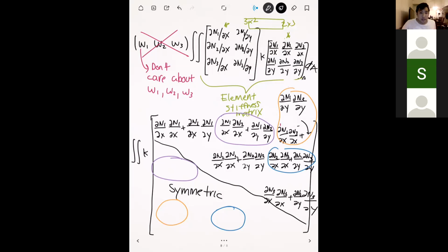Okay. So it's a doozy. It's a lot of calculations, a lot of multiplications, and a lot of adding, and they all involve our shape function derivatives. Doing these by hand is going to be a huge pain because you have to do all these calculations manually. But with a programming language, if you can leverage the matrix multiplication in MATLAB, this is actually a lot simpler to do in code.